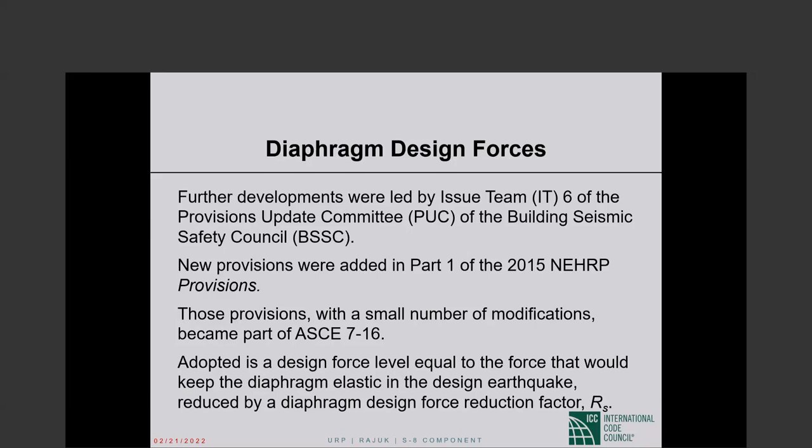Anyway, there are a couple of things that I think are important. You cannot have anything that will... what do I want to say? The structures will need to deflect freely with whatever you have installed in place. So the gap has to be maintained. You cannot let it be filled with debris or whatever over the years, because then you don't have a separation.